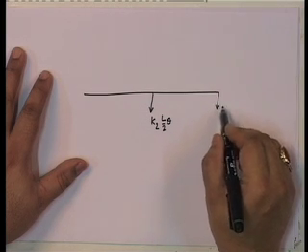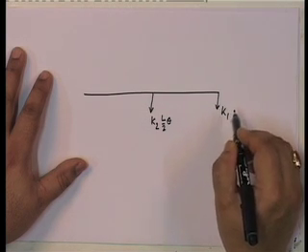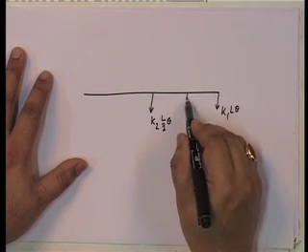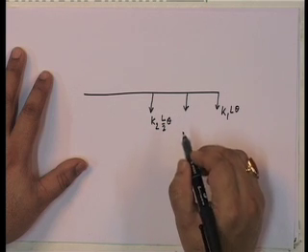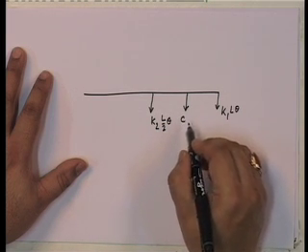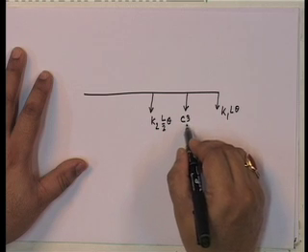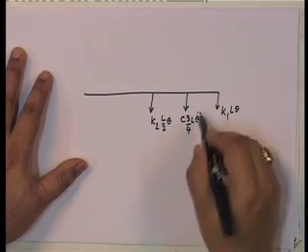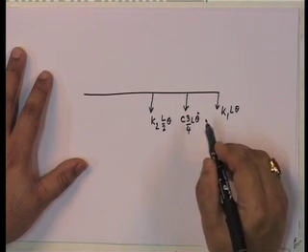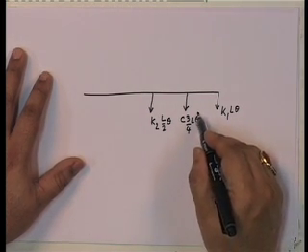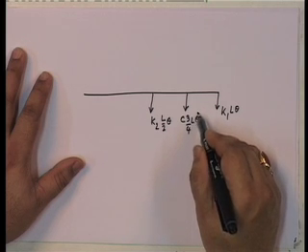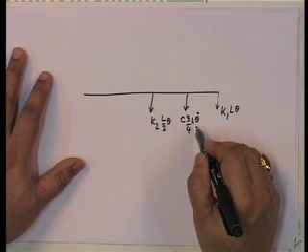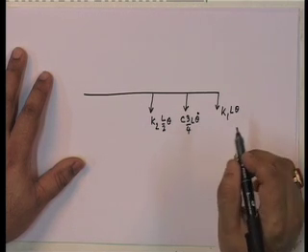This one is going to be K 1 L theta. Over here, we are going to have C into 3 by 4 L theta dot. Remember, the dashpot force is proportional to the velocity. So, it is 3/4 L theta dot, where displacement is 3/4 L theta. If you differentiate with respect to time, that becomes theta dot.